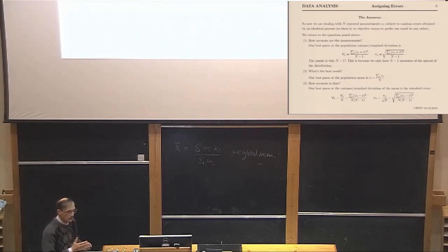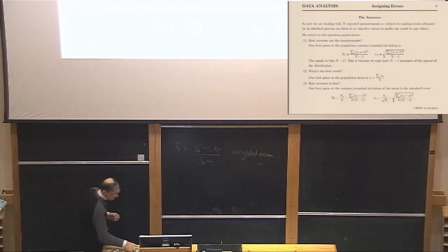So in order to give a coverage, which is a different thing from a standard deviation, you have to multiply the standard deviation by a coverage factor. So if you want to give something that encompasses the data, the whole likely spread of the data, you have to multiply the standard deviation by 2 or 3. And that's called a coverage factor, and if you're doing that, you should certainly say that you're doing it.